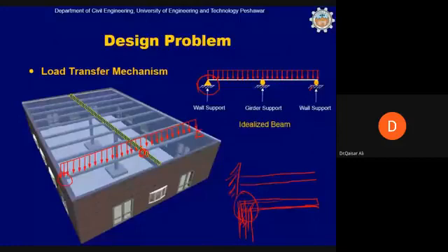But why have we assigned these? Why have we idealized these two supports as roller support instead of idealizing them as hinge support? Because in the first case, we idealized this as a hinge support, the second is a roller, and the third is a roller. There is a reason to this. Though from the analysis point of view, there will be no difference if you analyze this system with a hinge support at the midspan and hinge support at the extreme edge of the other wall. From the structural point of view, there will be no difference because the bending moment is not resisted at the extreme ends, and because there is no horizontal load, there will be no horizontal reaction. There will be vertical reaction and a negative bending moment at the support. There will be zero bending moment at the ends. Then why have we idealized these two supports as roller and one of the supports as hinge?